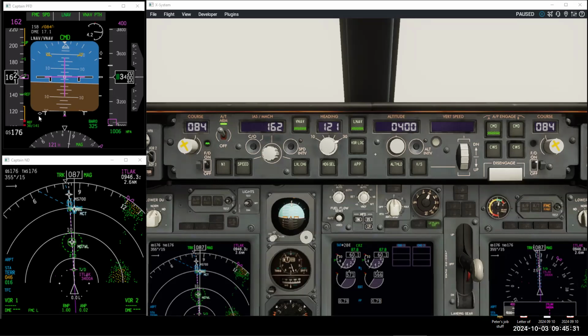If you notice here, the small delta is actually the center line of our track in the RNAV process, RNP AMP. And this is the vertical path here. Remember, there's no ILS tuned. These are part of the nav performance scale. And we are in VNAV path, and we will have a look at the vertical path later.